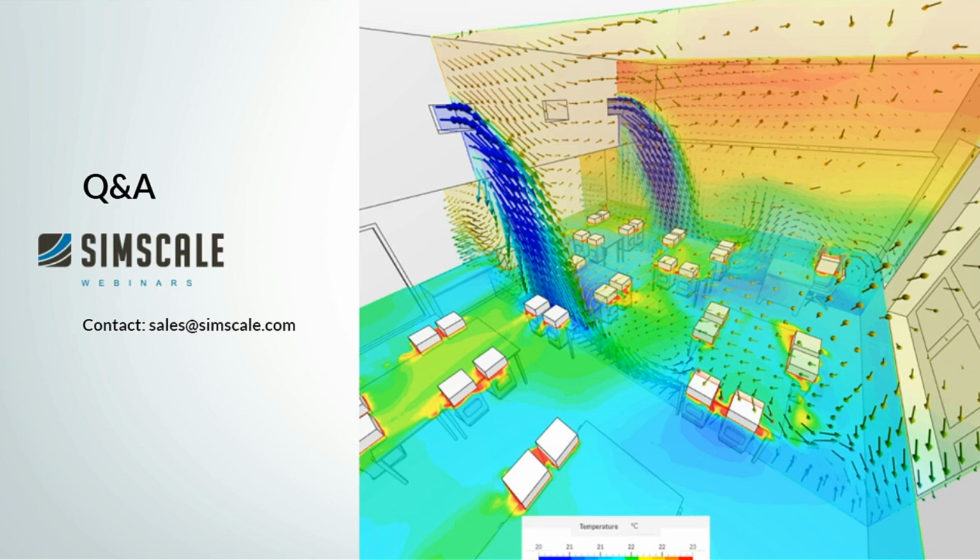Thanks. Then there's a question regarding what we can extract from the results, if you can get any statistics of specific areas of interest or an entire plane. Yes, that's possible. We have what's called, I think, the bulk calculator in the post-processor, where you can select a specific surface and it gives you statistical quantities like the min, max, and average value of a specific field on the surface, and also computes surface integral quantities on the surface. It can also be used on cutting planes.